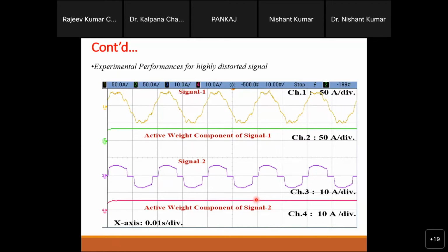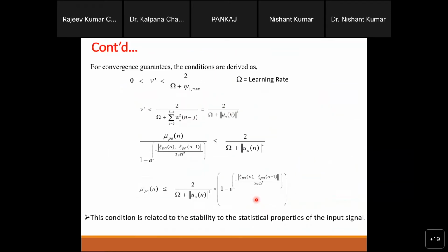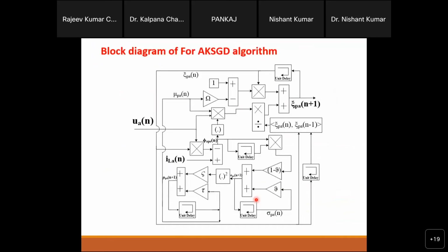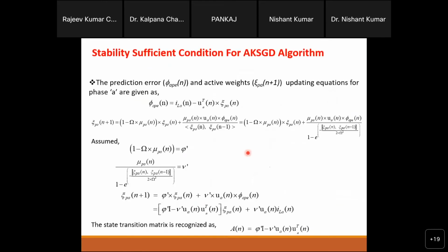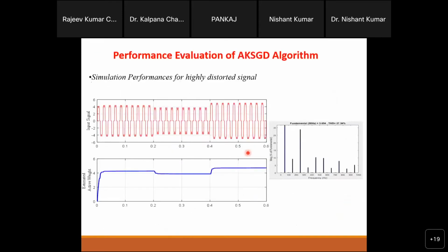Definitely, in this entire calculation, we have one step delay. You will see that, then you will realize that here we have one step delay, but this delay impact is less in this system because, as I told, we are not going to calculate the error and use it to update. Here we are also predicting the error for the next step. Through this way we can sort out those delay issues.